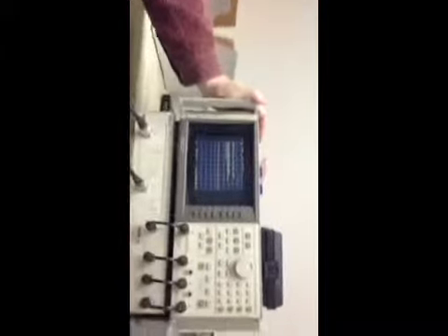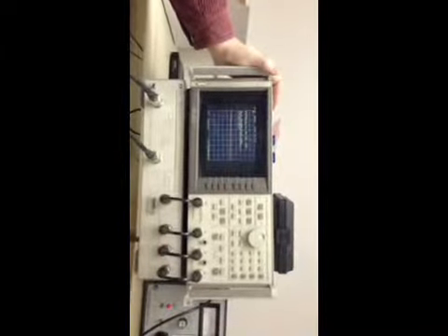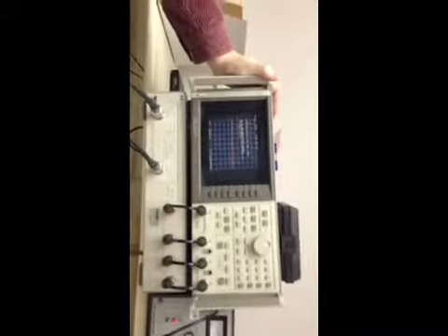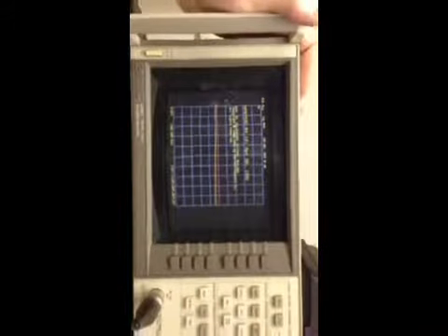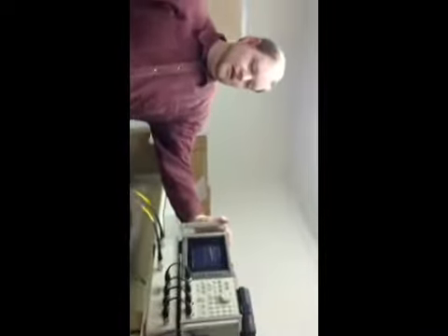We're reporting here from Val Avionics, the new lab, so that we can do some work on our NAV 2000 project. This is Group 30 signing in. Today we're working with this network analyzer. It gives us the frequency domain response of a filter without having any power applied to it, and it operates between 300 kilohertz and 3 gigahertz. So it'll give us a good signal of how the signal flows through and how much attenuation we're getting.